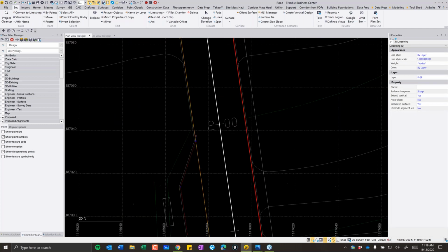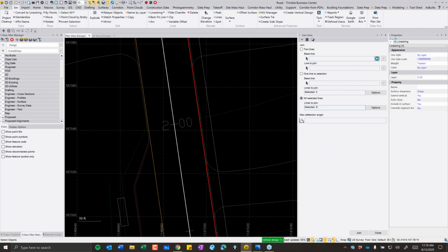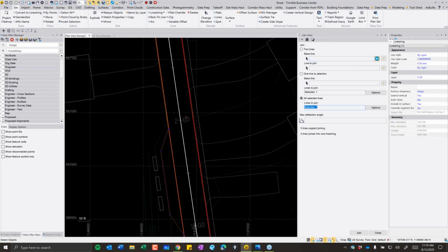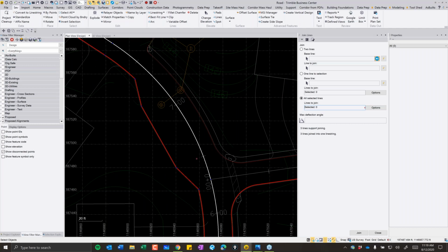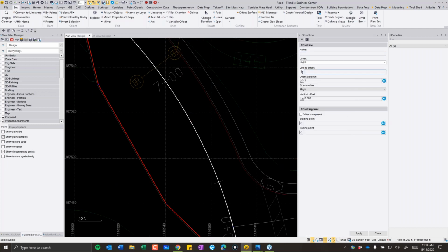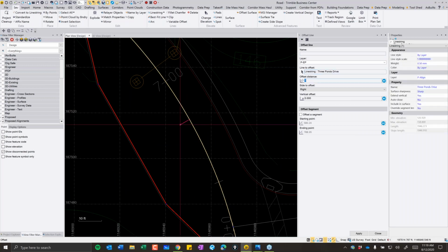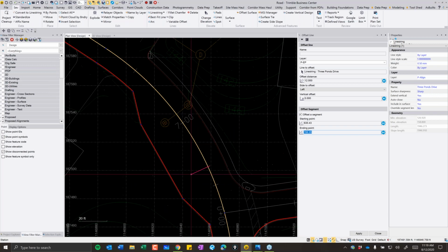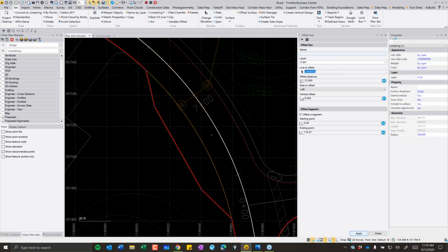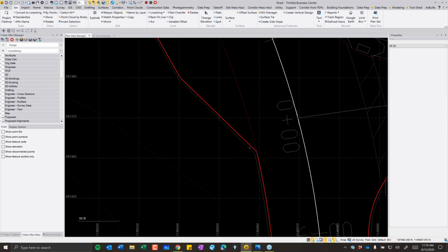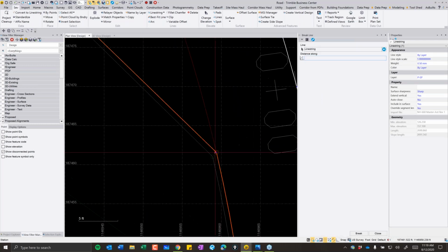So one of the key things that I feel like is important, Pat, and maybe you can comment on this, is strategically when you start planning out a model, you've got to work out how you want to build it. You've got to work out what's going to be elevated off what, in what sequence, and what line work you need to achieve that strategy. So in this case, you're building additional lines that weren't in the CAD drawing to put the pavement through at a fixed cross slope before you get to those push outs, whatever those are, parking areas or turning areas. So you have to plan out the line work ahead of time before you really start diving into the vertical design. You can do it on the fly and keep adding it if you need to, but it's easier if you think through that before you start, right?